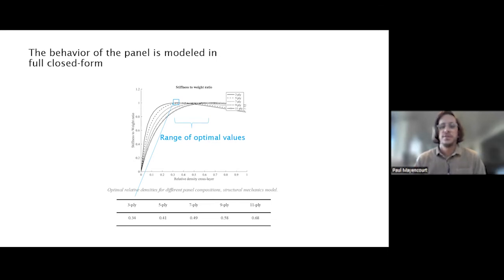And we looked at stiffness specifically because it is a better proxy in terms of structural capability for these panels. Most CLT structures or panels are governed by stiffness or displacement constraints. So you want to make sure that the panel stays stiff enough, and the strength will not be an issue as much. Even though we looked at stiffness here, the strength was always part of the calculation. So all these panels are structurally sound in the sense that they can support the load, but also be stiff enough.